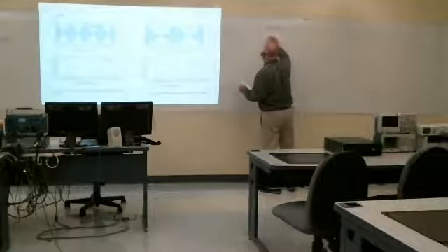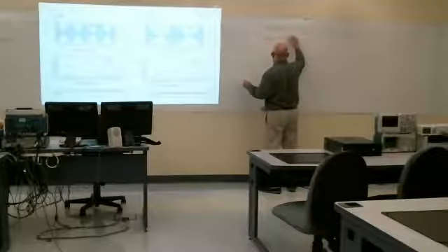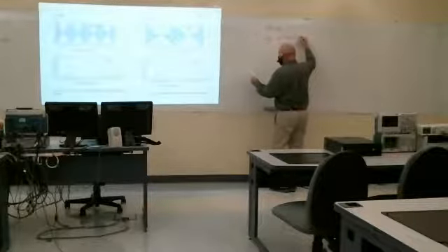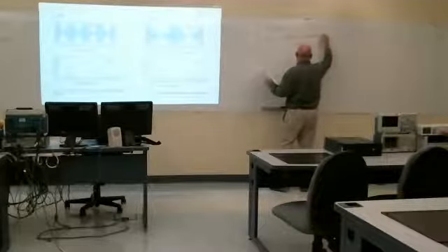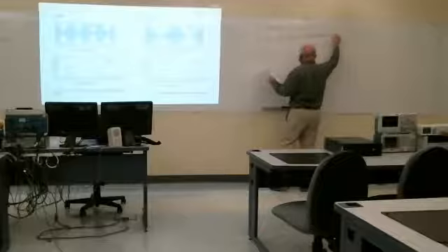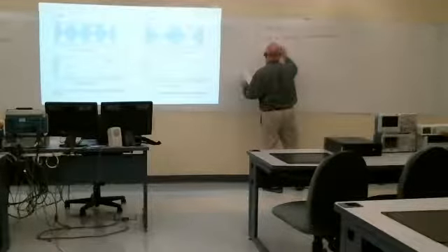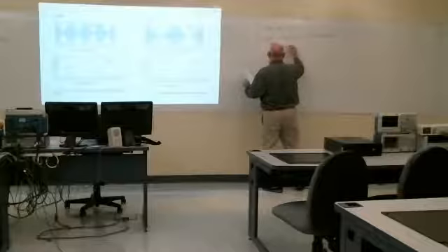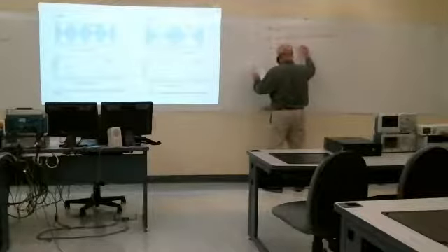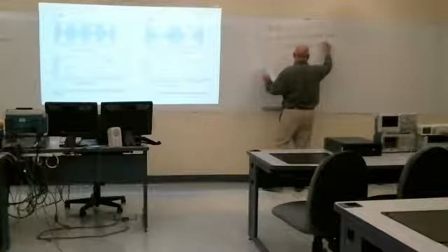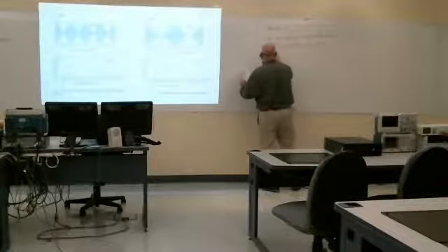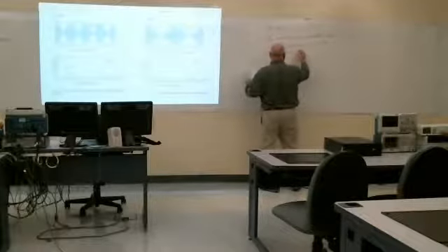So the idea in our Fourier theory tells us this: by multiplying a modulated signal by a sinusoid, I've just been using cosines in my examples, but sine would work as well, we can shift the spectrum in frequency.